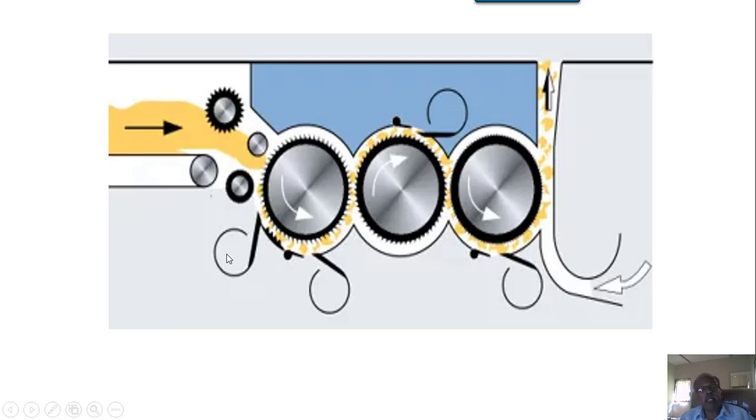Wherever the trash is released, a suction will be provided and that will dislodge the trash there itself. So in sequence that will go on happening. For the second beater you can see at the top the suction is provided. Suction intensity is another setting that is required to be done depending upon what beater speed you have, what distance there is between the assisting element and that beater, and what intensity of the trash is there to get adhered to the cotton.